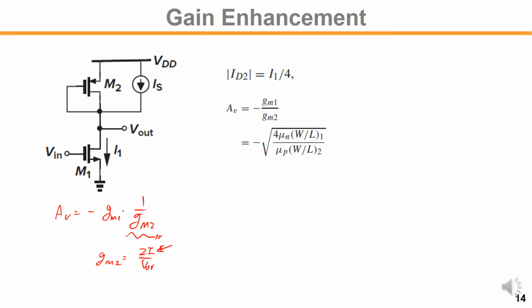then it is difficult to achieve very large gain, because sharing the current only results in small gain. The only variable you can play with is the overdrive voltage of M1 and M2. The overdrive voltage range is not that large, so to change the overdrive voltage, you have to change the device size.